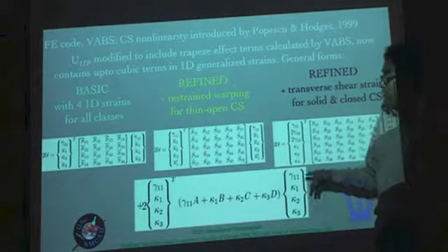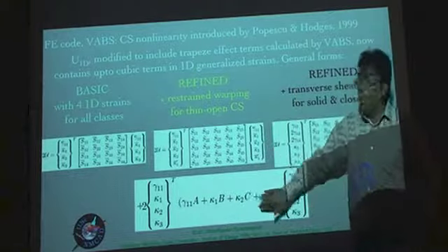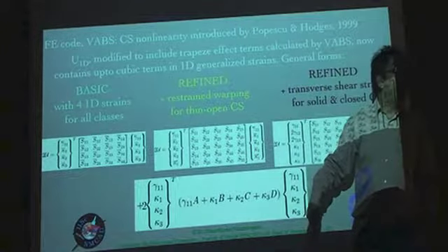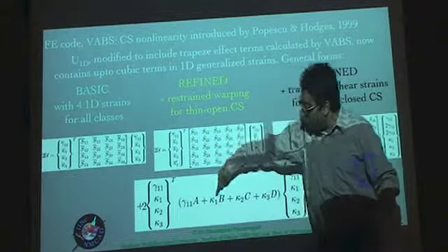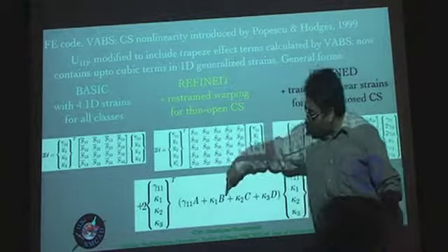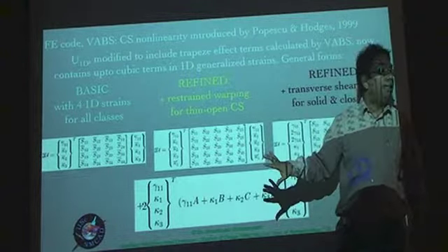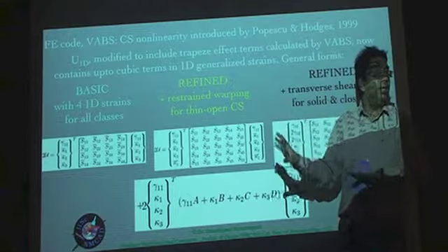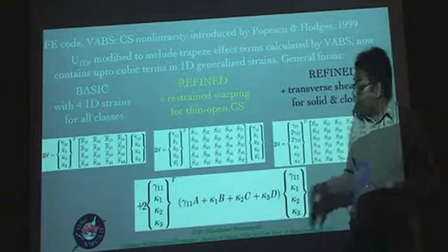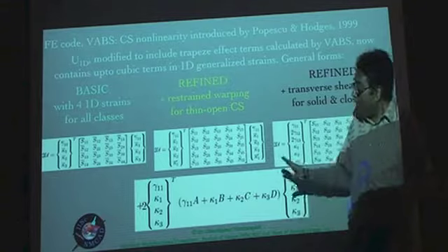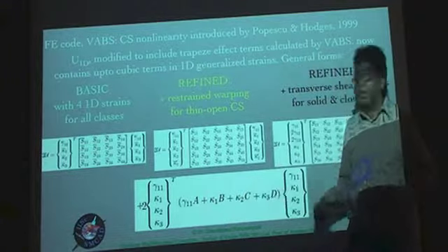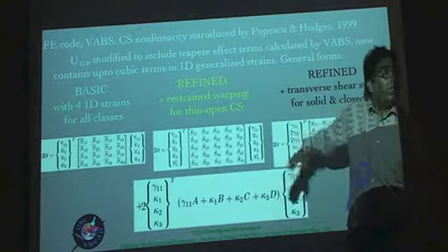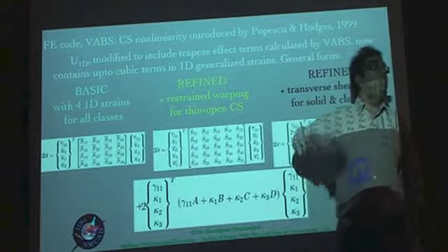So for these nonlinear terms, as you see, you don't have in between now a matrix of constants, but a matrix which is linear in the 1D strains. It is linear in gamma 11, kappa 1, kappa 2, and kappa 3, where A, B, C, and D are 4x4 matrices, and each one of them consists of constant terms. Of course, they can be fully coupled in general, fully populated in general, making all kinds of couplings possible. But you have only linear terms in the matrix itself, and then because you have quadratic because of this, in the terms of the contribution to the energy, it becomes cubic.